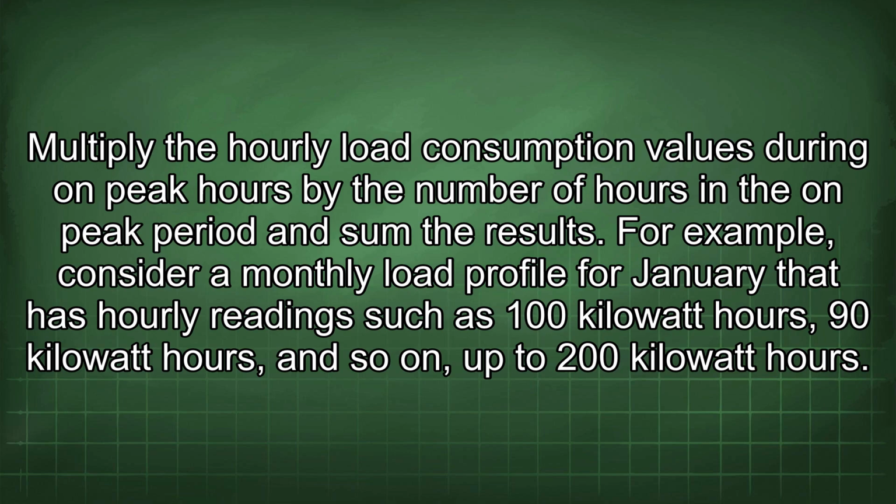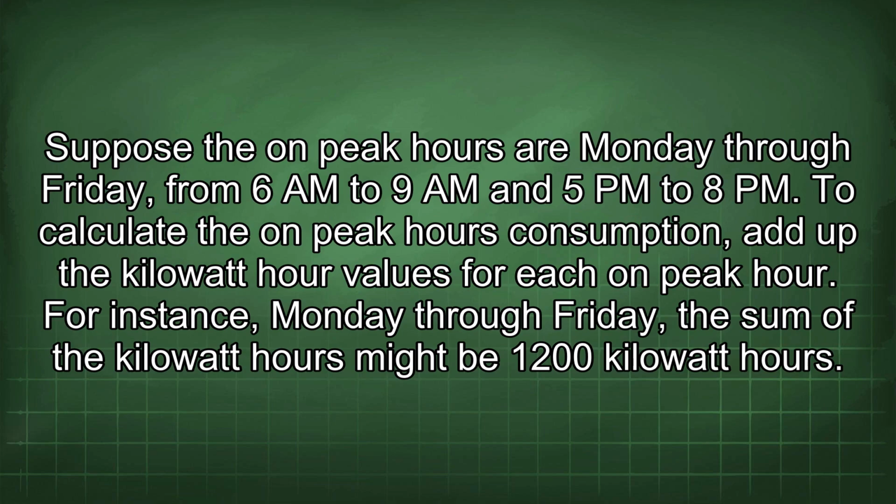the results. For example, consider a monthly load profile for January that has hourly readings such as 100 kilowatt-hours, 90 kilowatt-hours, and so on, up to 200 kilowatt-hours. Suppose the on-peak hours are Monday through Friday from 6 a.m. to 9 a.m. and 5 p.m. to 8 p.m. To calculate the on-peak hours consumption, add up the kilowatt-hour values for each on-peak hour.